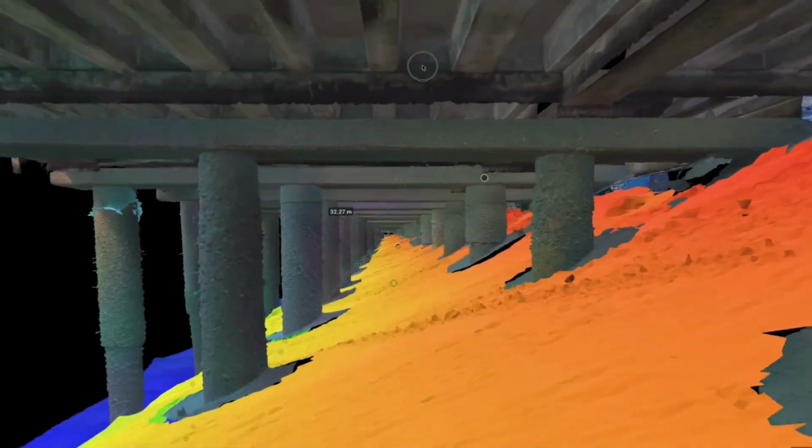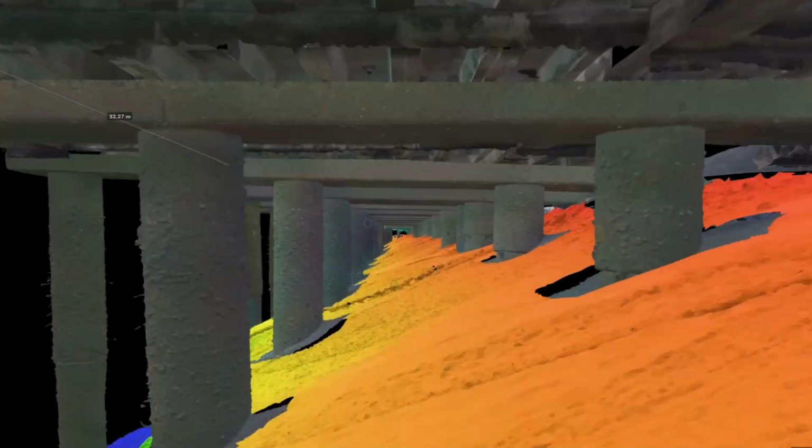And you know, you did the photogrammetry in the air. Making the photogrammetry underwater is extremely complex. You have so many different variables that you need to take care of, and you need to understand what is happening, because you have salinity, you have turbidity, you have the reflections on the dome. The dome gets deformed, and every little bit of variables attacks your photogrammetry or SFM procedure, and then you get the